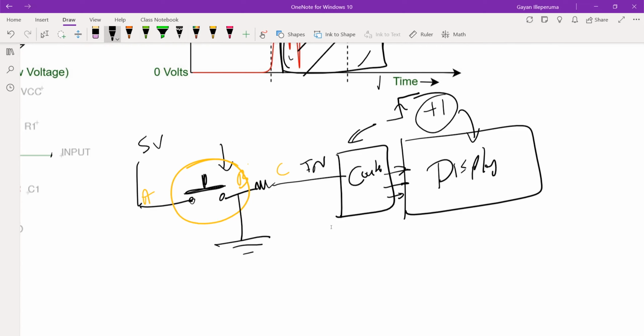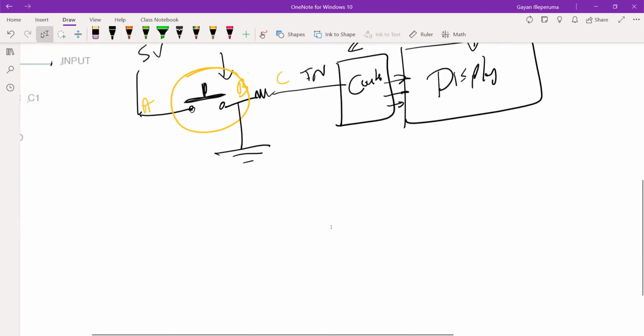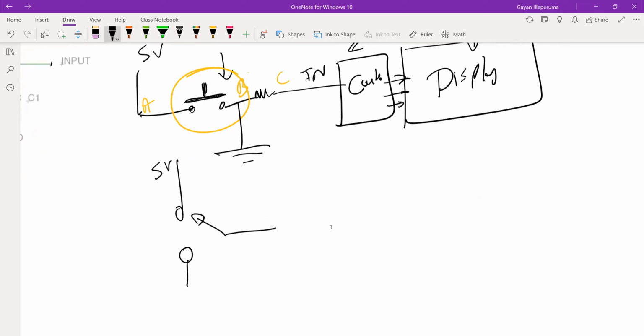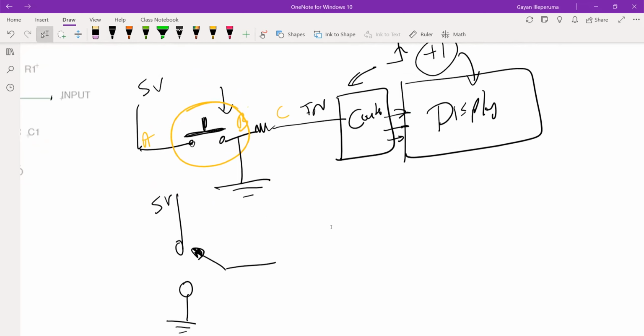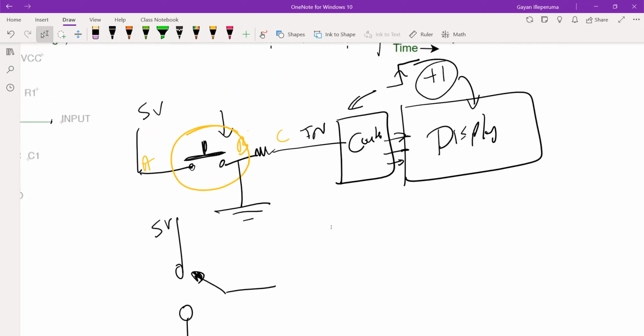So instead of this, we can use an SPDT switch, where one end is connected to the ground and the other one is connected to the 5 volts. Yes, that's another possible valid choice. You can have one going to the 5 volt, one going to the ground. Yes, that's a valid solution. But let's say I want to keep a push button because this is a little bit expensive, and you rarely have this kind. No, you have this kind of push button sometimes, but usually this comes in a different form factor, right?